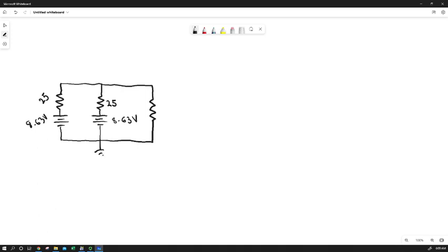Okay, so here's our circuit. Here's our 50 ohm load resistor, and that's the circuit we're powering. And I had mentioned in that video that in this case, the current that's going to flow through this load resistor is really dependent on the voltage at this node A up here, because we can apply Ohm's law directly to that. So if we use green for current flow, we can apply Ohm's law and show pretty easily that I load is equal to the voltage at A divided by 50 ohms. And that's just using our parallel circuit theory.